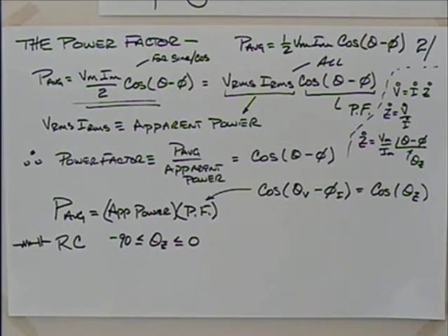If it's predominantly capacitive, it's pretty close to minus 90. Some of you in lab, hopefully you didn't walk out thinking you had new phenomena there at minus 93 degrees or something. That gave you a negative resistance, didn't it? Okay, before you turn that in for patent, you probably would recognize that that small negative resistance is due to error in your measurements. About the best we can do is get to minus 90.